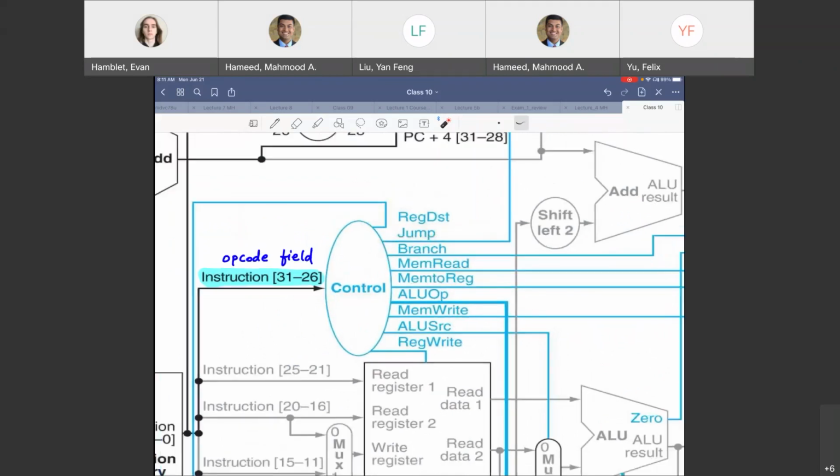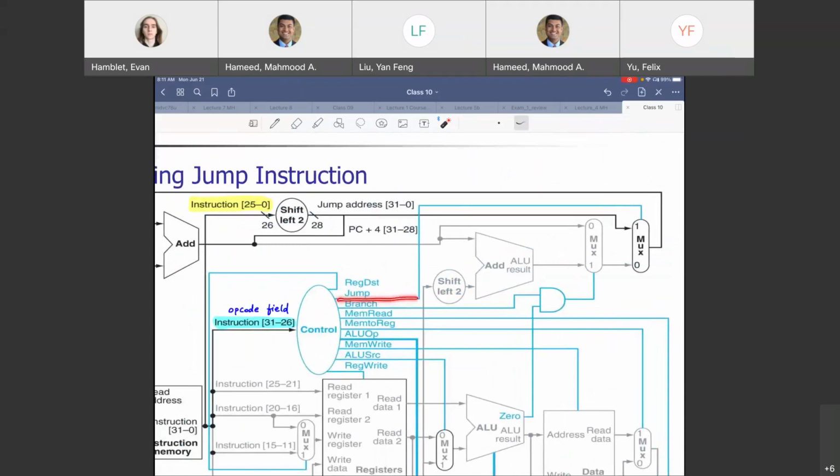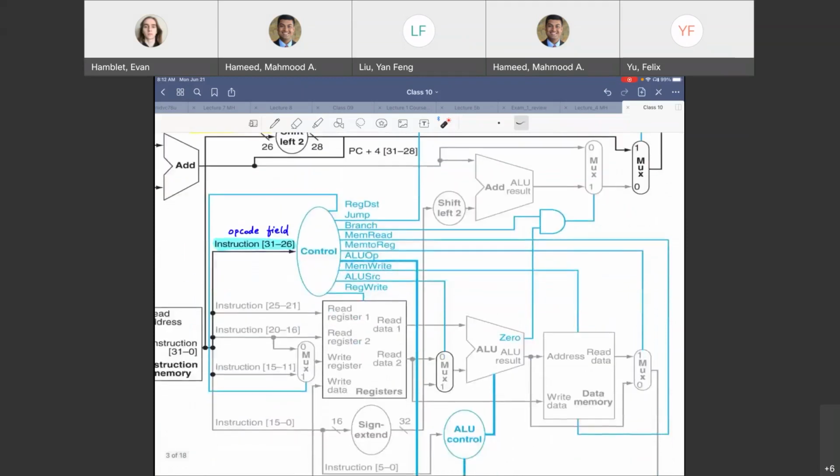And that line is going where? That line is essentially functioning as the select line for that mux. So that means if it gets asserted, you will pick up the 32-bit address that you had computed just now. See that? So data path, control, both of those combined, you have your computer architecture, right? So this one, we are adding control.